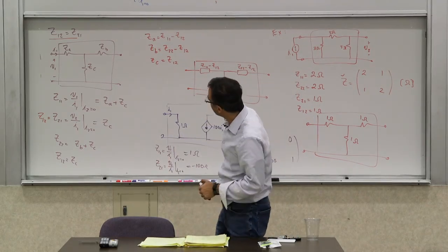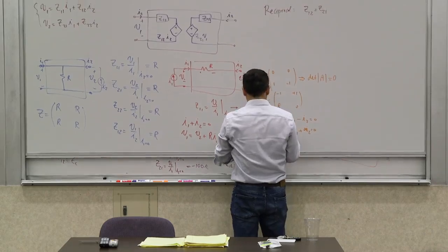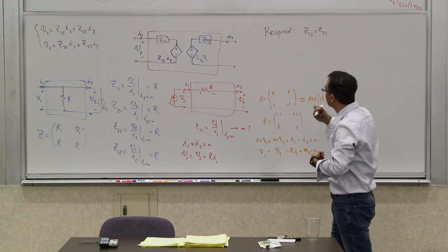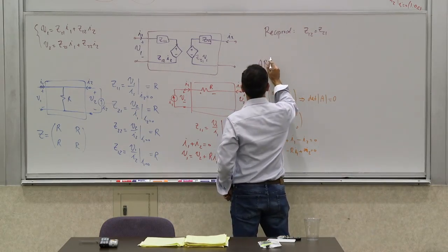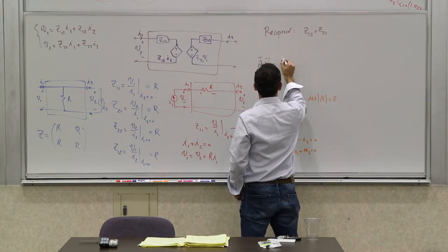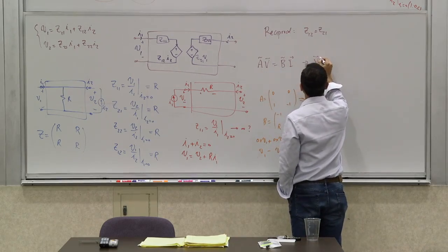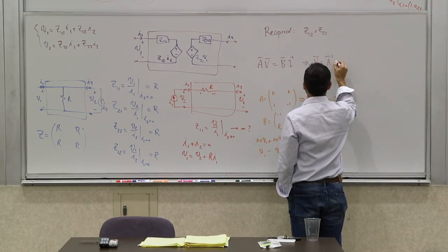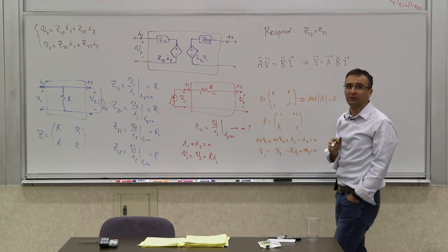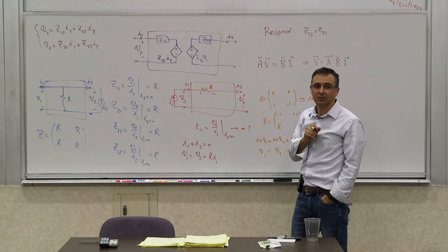So now we still had a problem, if you remember. If you go back to this expression, in this example we saw that we had no z parameters. That arose from the fact that in our original matrix calculation we had A times V equals B times I. To determine the z parameters, we calculated the inverse of A, which in this case didn't exist, and applied it to B. So what if A cannot be inverted? Are we done? Is there no way to characterize this thing, or are there other ways to characterize it?